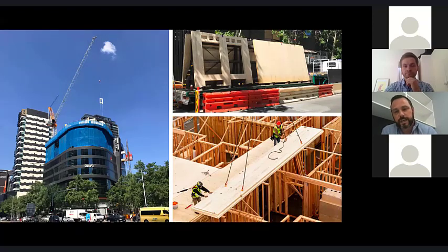And then you need a crane to come in to drop the CLT floor in, albeit a floor cassette. We did one in Melbourne for former Australand. We used a tech beam floor cassette, and craneage was needed to lift each of those individual floor cassettes in. And my point here is that that works very well when you can have mobile cranes, because for a large section of each floor cycle, you don't need craneage to lift all the wall frames up. So if you've got a lot of downtime and your crane doesn't need to work, generally you want to be supplementing with mobile cranes.